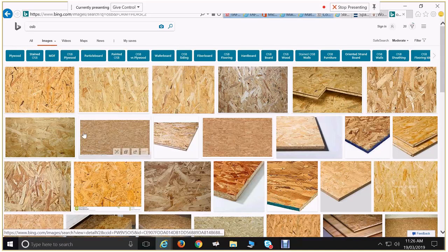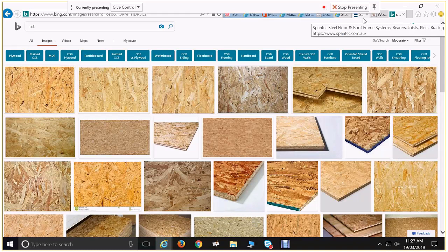Does everybody know that stuff? Has everybody seen that stuff before? Yeah. So that's oriented strand board. There's the Gunnersons are the supplier, but then there's some other manufacturer that manufactures it. Anyhow, that manufacturer says, use this OSB, it provides this many kilonewtons of restraint for this meterage if it's fixed in this particular pattern for this particular size. So rather than referring to the timber framing code, you can just refer to their product literature and use this for your sheet bracing. Because it's really cheap, that's becoming the mainstay of what everybody uses in terms of sheet bracing. But over garage doors, that might be different. I'll have to have a look at that for water resistance and also for additional strength. Because they put the bricks, you put the cable.